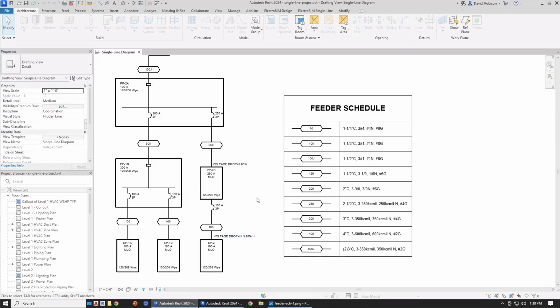So if you want to change a wire size, you don't come in here and say, okay, I'm going to change this 250 to a 300. This is actually a good example. We've got a system, we've got voltage drop here. We're over 3%. We really actually need to change this feeder size. Previously, what you would do is you'd cross out that 250 or erase it in CAD and you'd write in a 300. And that's how you get that new wire size.